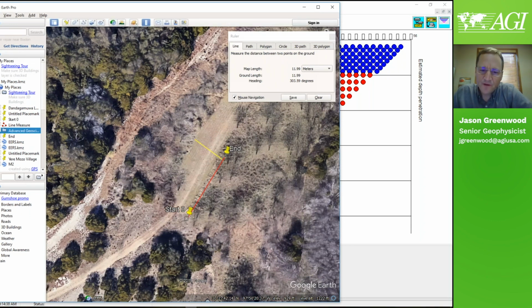That's 26 minutes. To put down 28 electrodes at 1 meter, this red line is 28 meters, that would take about 15 minutes in this open field. So for project planning purposes, you may know when you can show up on site. 28 electrodes, it's going to take 26 minutes for the machine. So you can definitely do probably every, if you're quick, once you get everything laid out, you can actually have 2 men pick up this cable and move it over, and not have to deploy again. So it's not 15 minutes every time.